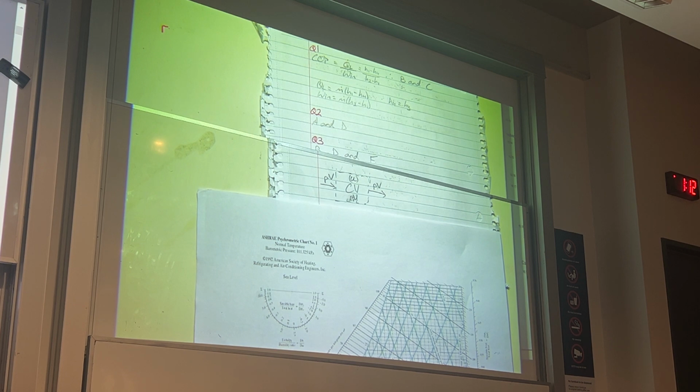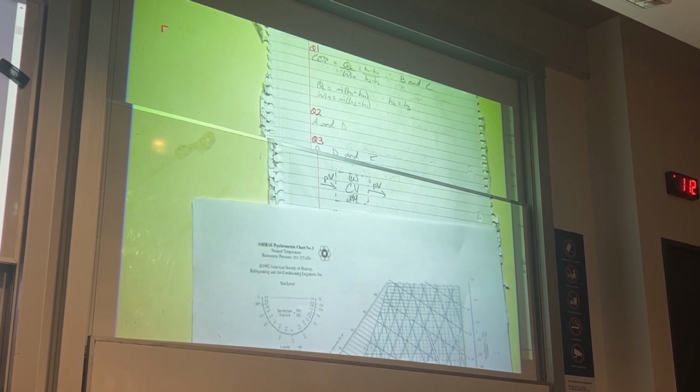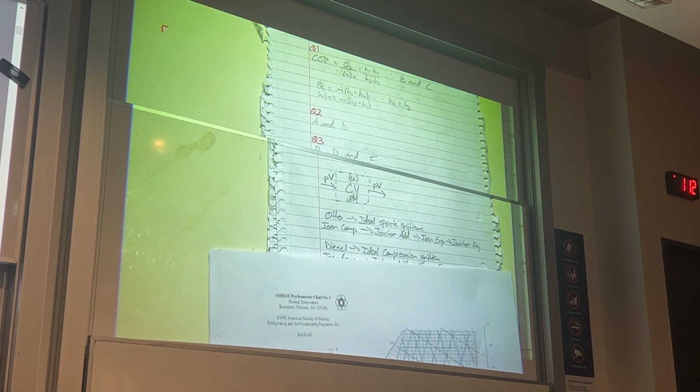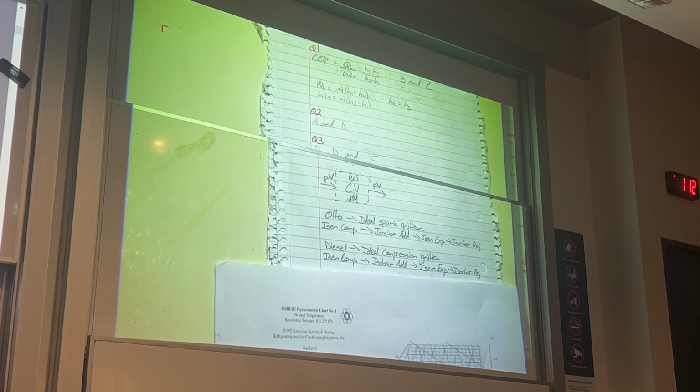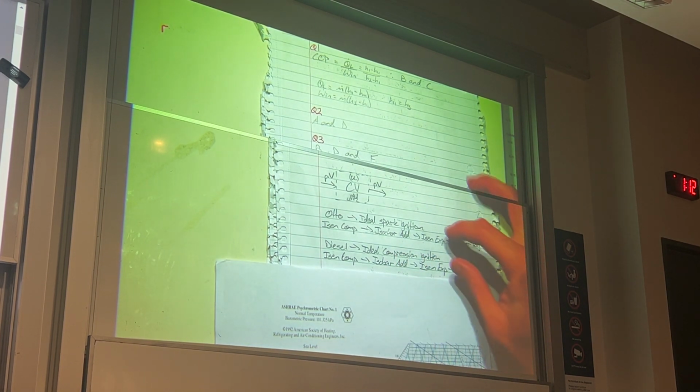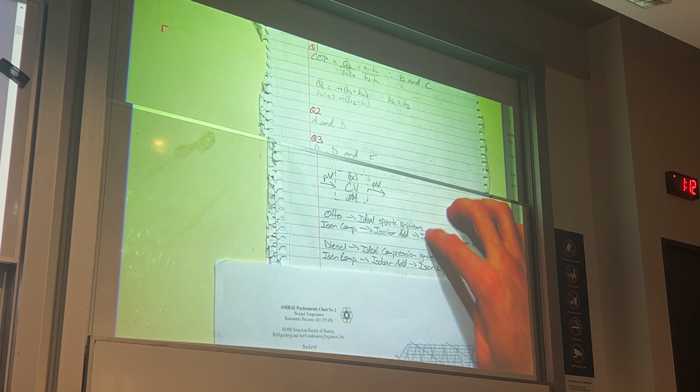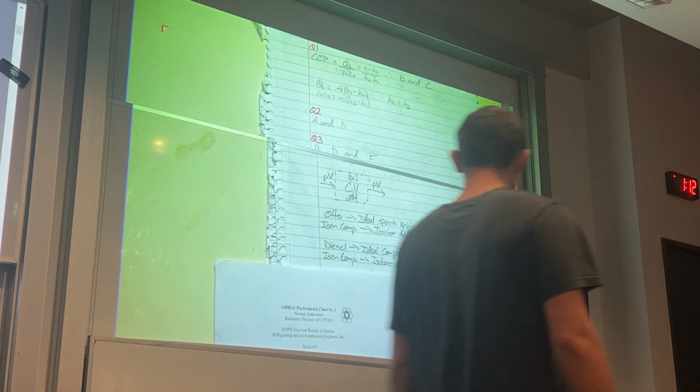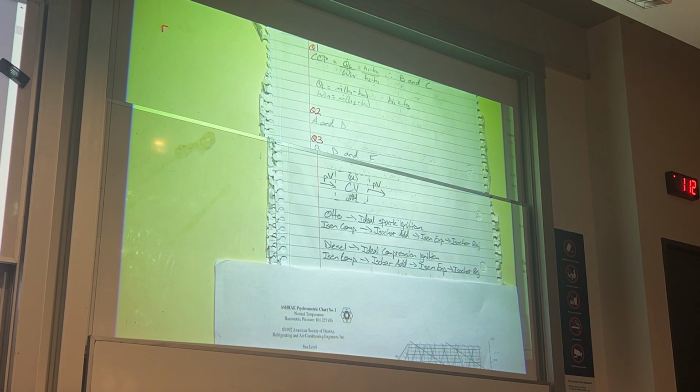The petrol needs to have a spark to ignite in the Otto cycle, whereas the diesel ignites at a certain pressure. Yep, perfect. So I've given a little summary down here. So you can see we have isochoric ignition and then isobaric ignition. But the key part here is we had an ideal spark ignition or an ideal compression ignition. So our diesel will ignite at some pressure, where our Otto cycle requires spark.